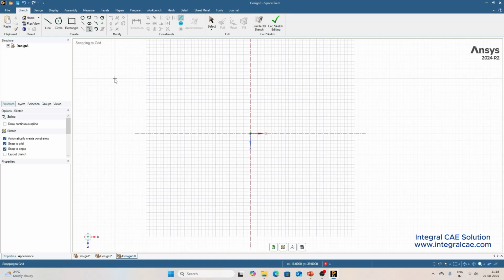Next option is called spline. This option creates a smooth curve from multiple line segments. Let's click on the grid and it will start the first segment. Then click next to create the next segment. This will create a smooth transition between the lines. We can create as many segments to make the shape as we would want. Clicking further will create more segments for this curve.